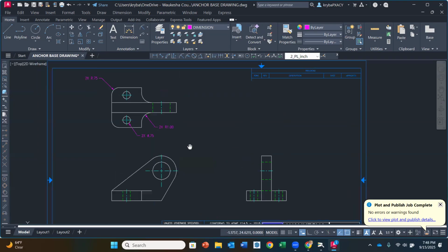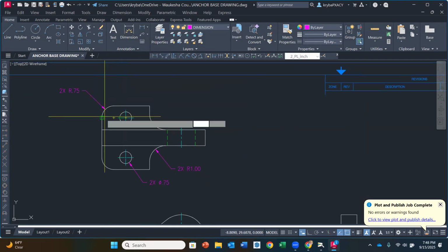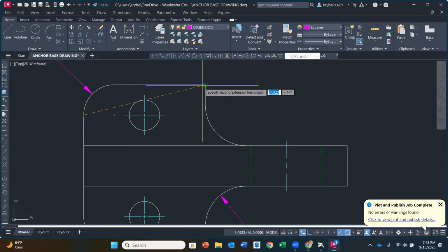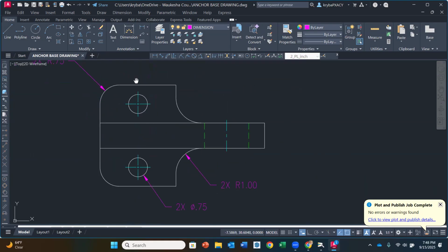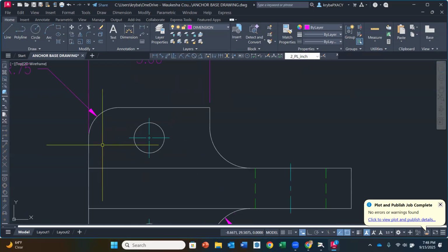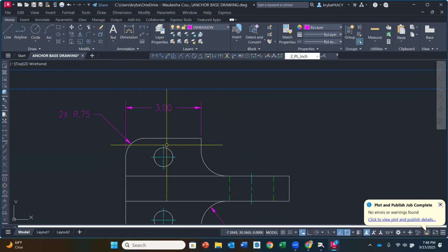Okay. So then now we want to put our linear dimensions on here. So I'm going to arrow down, go to linear dimensions, and here now, when we have a radius like this, we need to select the end of the flat part. Okay, left click there, and then I'm going to do this one here. It is going to be closer and it's going to look close, but that's okay. All right, it is what it is. If you wanted to, you could select it and move it out along that line. If you're bothered by it, I'm not. I'm not terribly bothered by it.